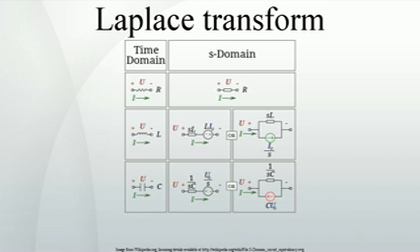The sources are put in if there are initial conditions on the circuit elements. For example, if a capacitor has an initial voltage across it, or if the inductor has an initial current through it, the sources inserted in the S-domain account for that. The equivalents for current and voltage sources are simply derived from the transformations in the table above.